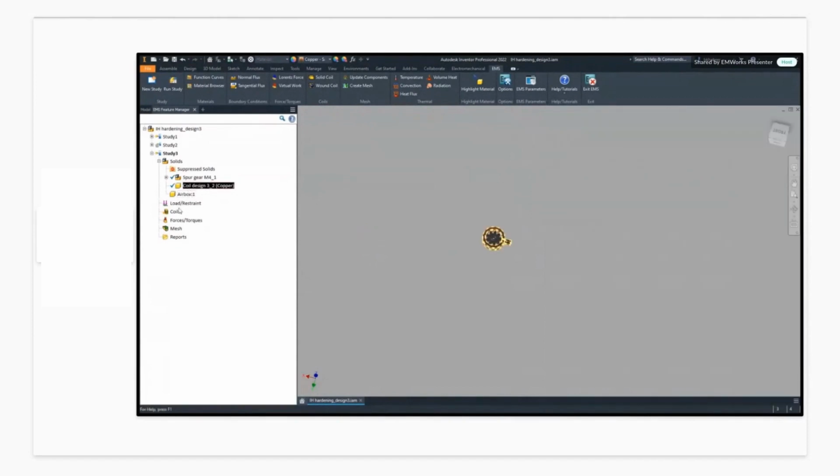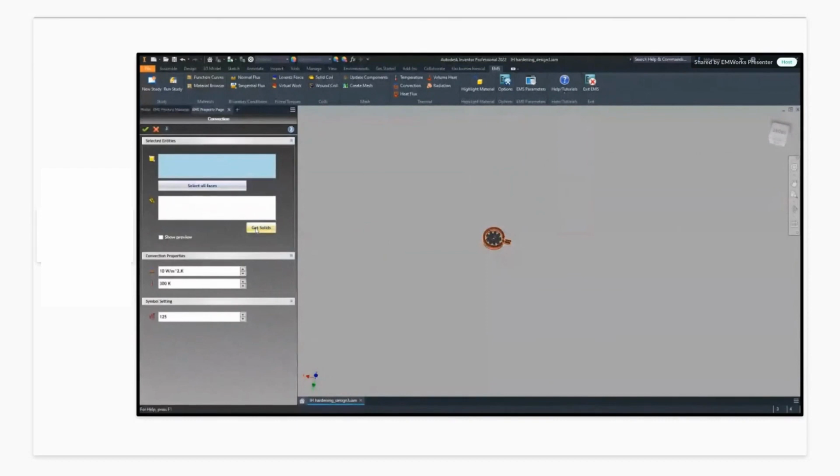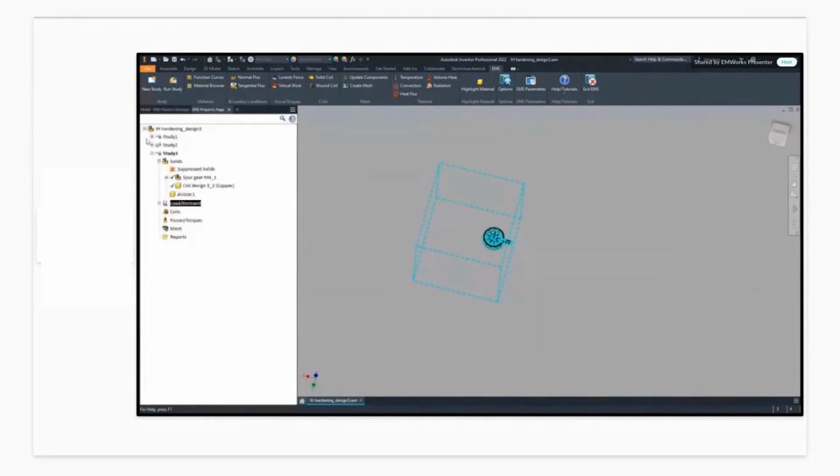Okay, so once you define the materials, the next step is boundary conditions. You don't need anything here, but when doing thermal, since this is a thermal coupled simulation, you only need to specify convection for your material setup. Here we will use air for the convection coefficient. As you can see, you can load the list of the materials here. So apply, and we can keep using the default settings. After you finish this boundary condition, you don't need to apply tangential or normal. Well, tangential is sometimes needed, but for thermal inputs, you mainly only need convection. But if you want to add additional boundary conditions, yes, you can do thermal, you can apply heat flux, radiation, and volume heat. It's power per volume, or per cubic meter.